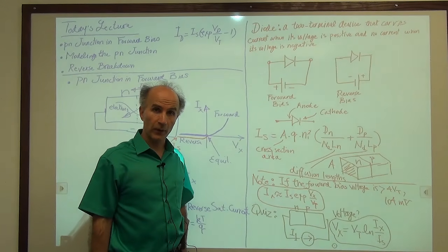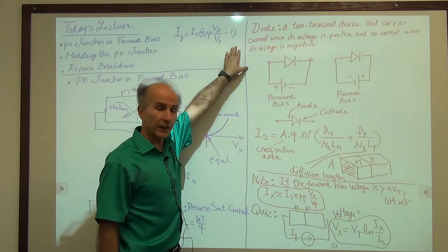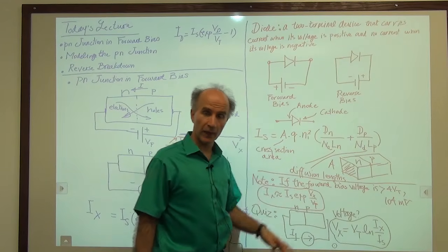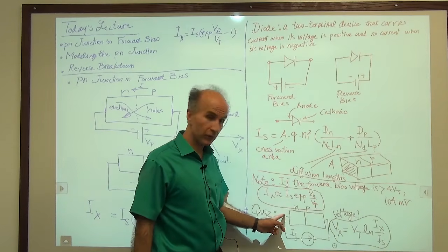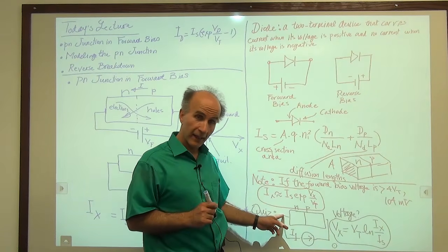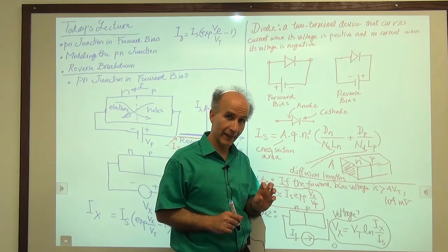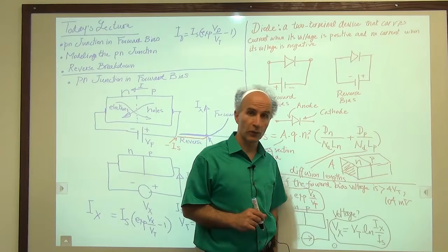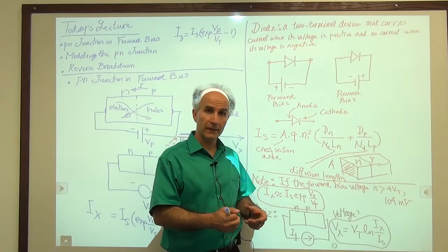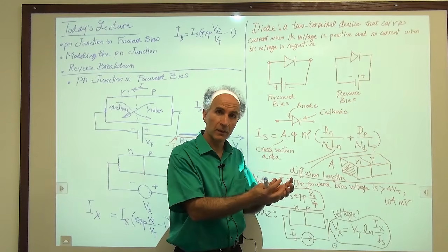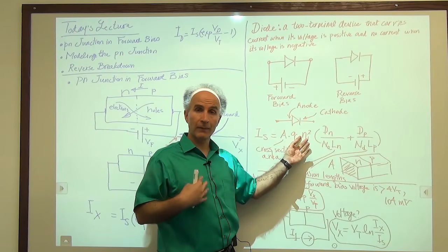So that's also an important equation. You have to remember both this equation, now without this one most of the time, and then this equation, again without that one. And this equation says that the voltage that you measure across a junction when it is forward biased and it carries a current of Ix is given by log of Ix over Is multiplied by Vt, 26 millivolts. Keep in mind that Is is constant when we buy that Pn junction. These are all properties of the Pn junction itself. They are not under our control from outside.